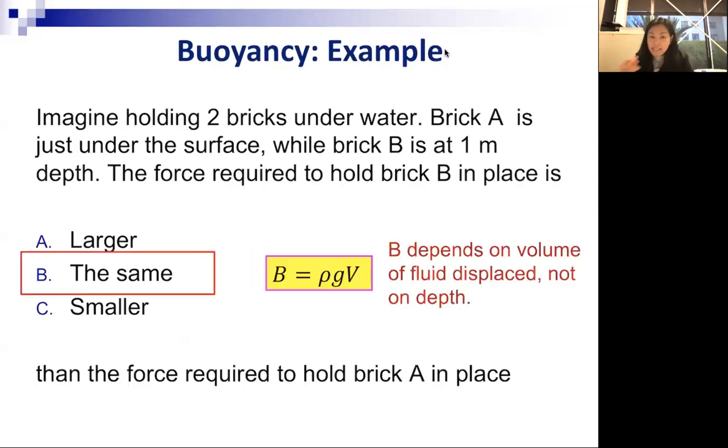The answer would be the same, because the buoyancy force only depends on the density of the fluid and the volume of the fluid displaced. If the bricks have similar shape and size, so the same volume, then they will displace the same volume, and therefore they have the same buoyancy force. In which case you should exert the same amount of force to keep them in place.